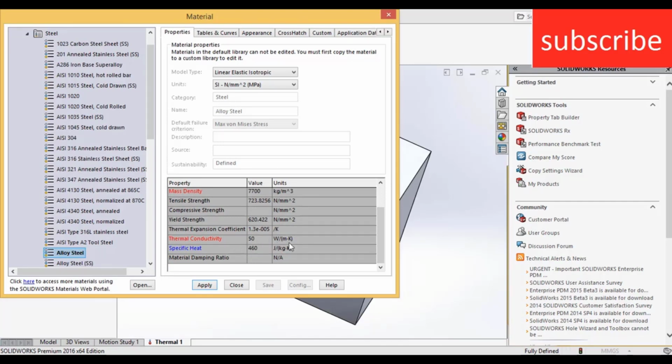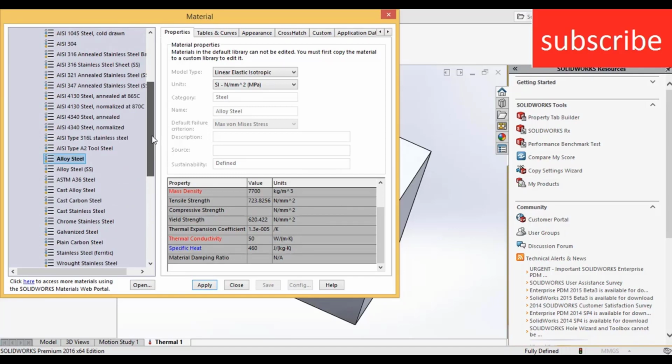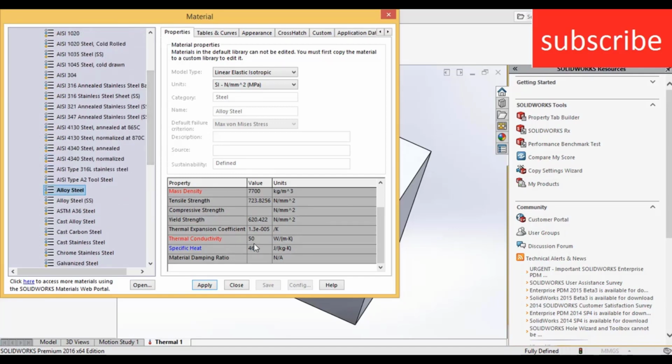For example, in this scenario 50 watt per meter Kelvin is given as thermal conductivity, so I am choosing this. You can choose any material as per your requirement, but make sure Solidworks shows the value of thermal conductivity, because in some cases Solidworks doesn't give the value of thermal conductivity.